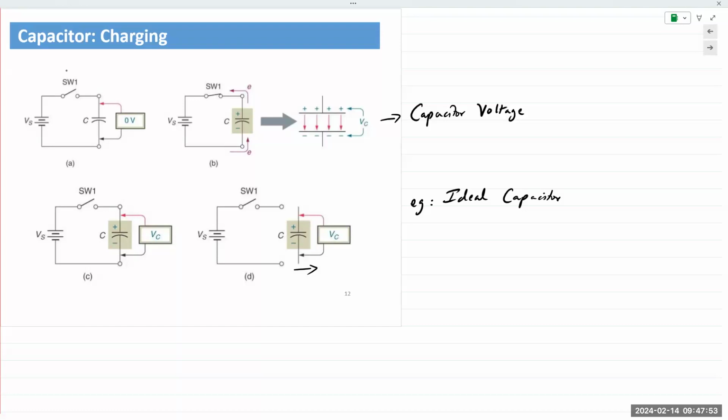But in real life, there is no perfect insulator. It might take minutes or hours or days, but that capacitor will lose the charge completely because the two plates are connected. Since we say they're separated by the insulator, we can also say they are connected by that insulator. So charge from one plate would seep through and discharge from the other end.